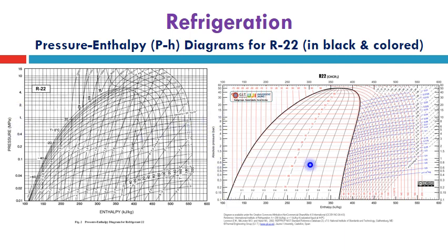The constant temperature lines are similarly and clearly shown: minus 70, minus 60, minus 50, minus 40 until reaching 0, then 10, 20, 30, 40, 50. The constant volume lines are shown here in meter cube per kilogram in blue, which may be easy to see for the user.